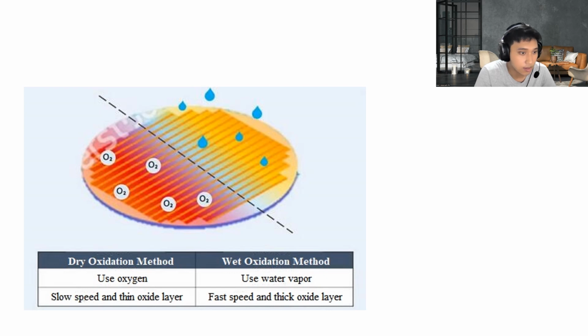In the oxidation process, it is also necessary to use dummy wafers according to the location of the wafers in the unit to protect the wafers and reduce the difference in oxidation degree.